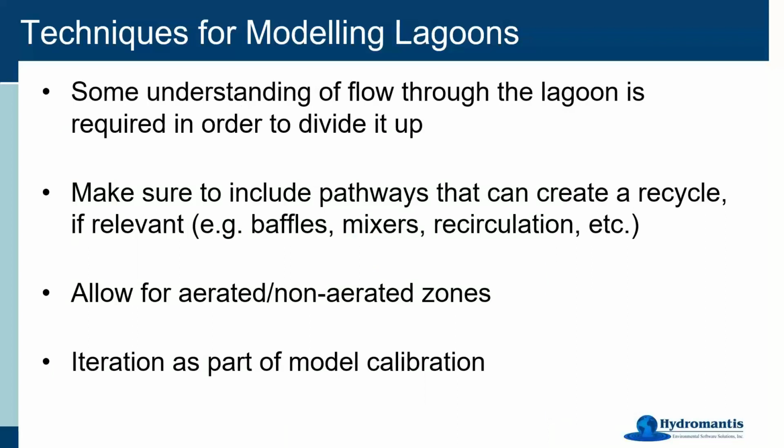So as I mentioned, we really ask a lot of questions when it comes to putting a lagoon model together, a lot of questions of the people who are running that lagoon in order to understand how it fits together. There are places where there are big baffles and recycle pumps and mixers and other things that are there deliberately to make it move in a certain kind of way. So that would be key information that you should definitely need to know.